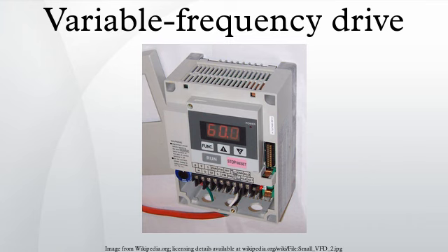With a VFD, the stopping sequence is just the opposite of the starting sequence. The frequency and voltage applied to the motor are ramped down at a controlled rate. When the frequency approaches zero, the motor is shut off. A small amount of braking torque is available to help decelerate the load a little faster than it would stop if the motor were simply switched off and allowed to coast. Additional braking torque can be obtained by adding a braking circuit to dissipate the braking energy. With a 4-quadrant rectifier, the VFD is able to brake the load by applying a reverse torque and injecting the energy back to the AC line.